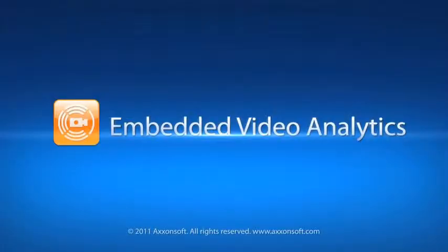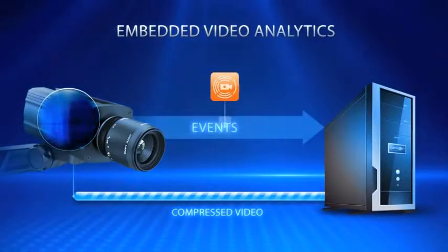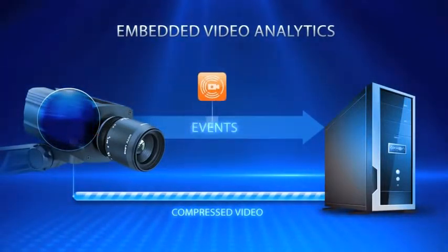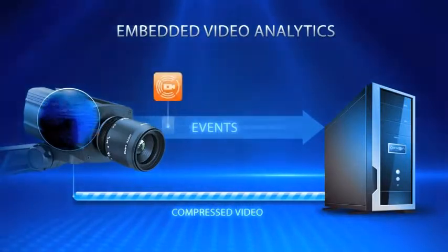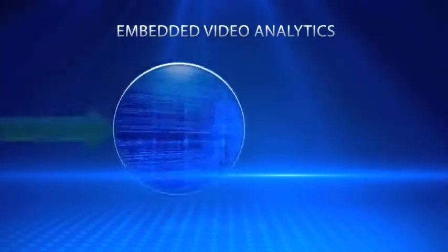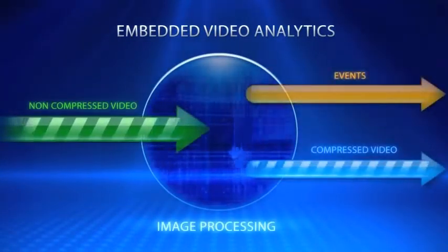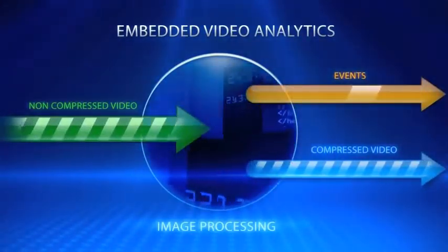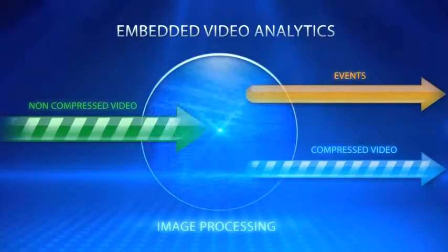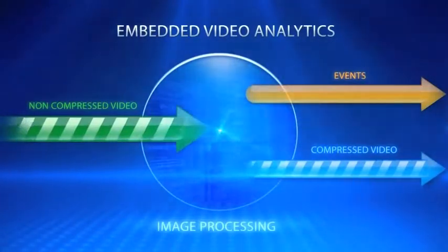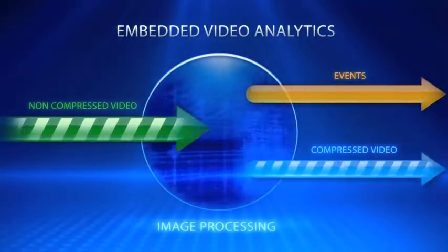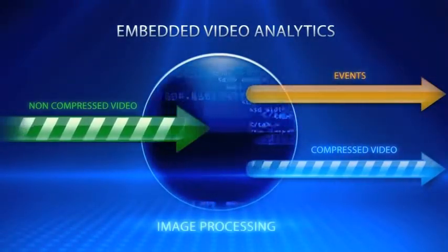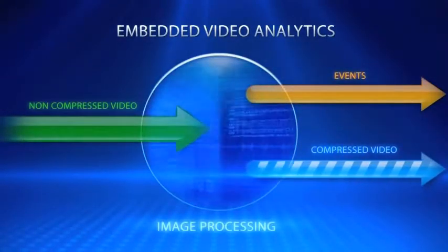Embedded video analytics. Axxon Smart Pro supports embedded video camera analytics. The benefits are lower CPU usage on the server and better video analytics performance. First off, embedded IP camera analytics process tons of video and feed the digest, i.e. metadata, to the VMS. Moreover, in-camera processors have access to raw, uncompressed video. This helps ensure more stable operation of the onboard video analytics under difficult conditions.